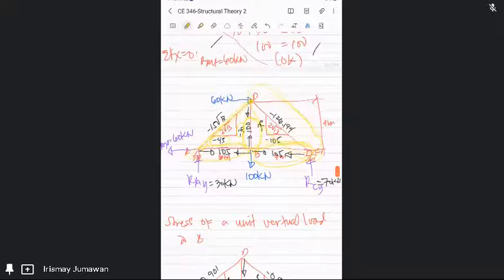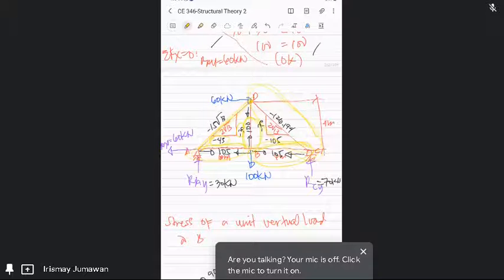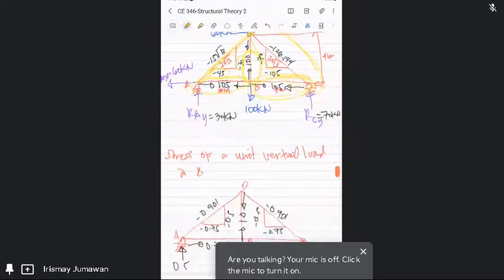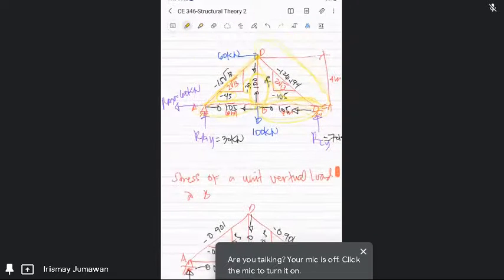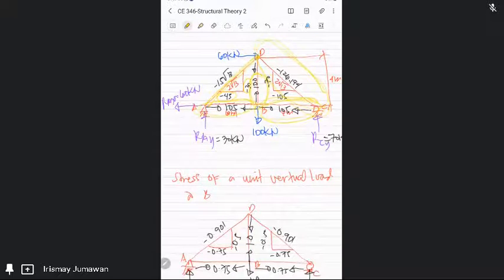You understand this, right? Once you do this, it is better to tabulate all the data so it is easier for you to look. So again, finish the bar forces first. You have negative 70 for member DC as the vertical component, so I need to determine the X component. I multiply 70 times 6 divided by 4, which gives 105. Then 105 times 2 square root of 13 divided by 6. So I check this at C, and it must balance.